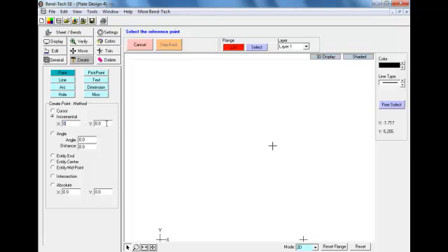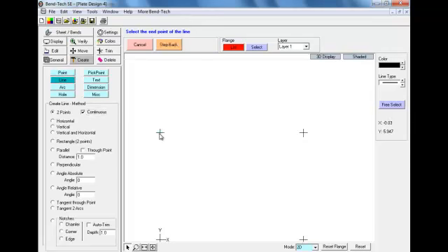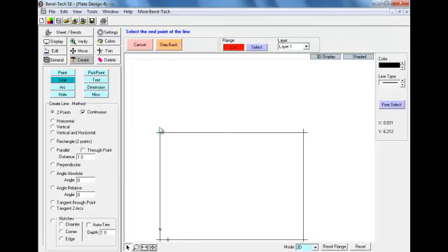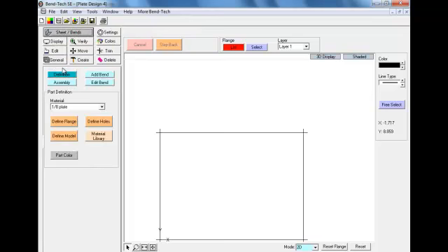We're going to start out by laying out our base flange. We will first select a couple points to make this flange. We also need to create our points on the y-axis. And then we can take these 4 points and combine them with lines defining our base flange.